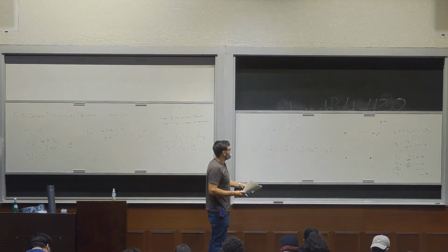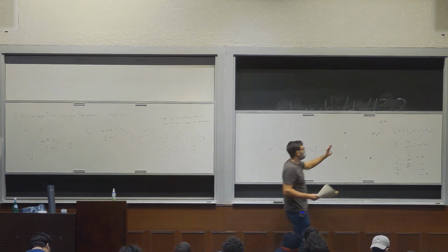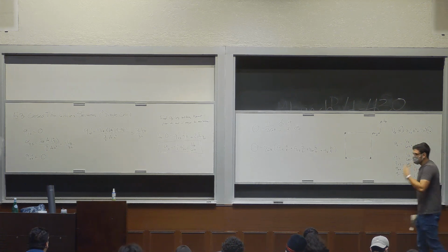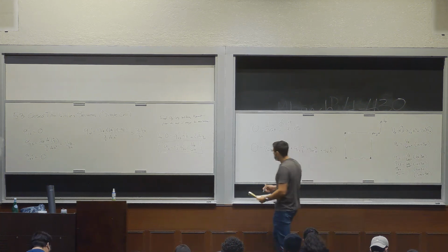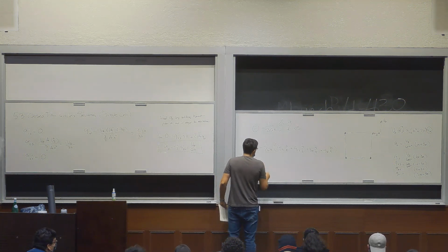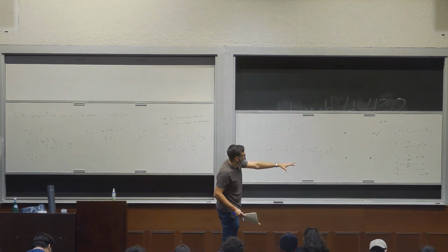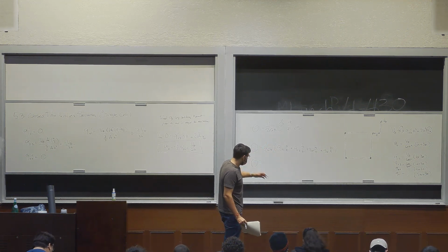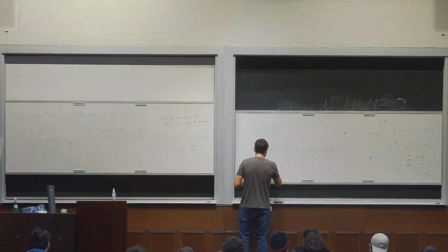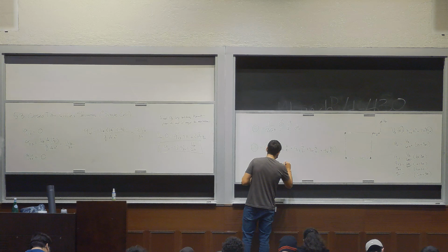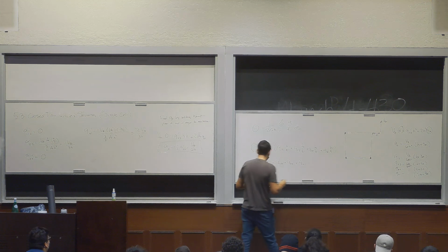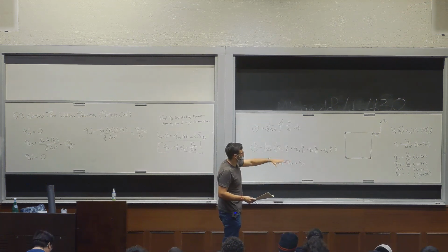The key here is that if this shear force, VZ, was acting at the location of the shear center, this rate of twist would be 0. So we set this equal to 0, and we plug in those equations for Q12, Q23, and so forth. We could simplify this to Q12 plus Q23 plus Q34 plus Q41 equals 0. VZ is a known value, H is a known value, everything's a known value.